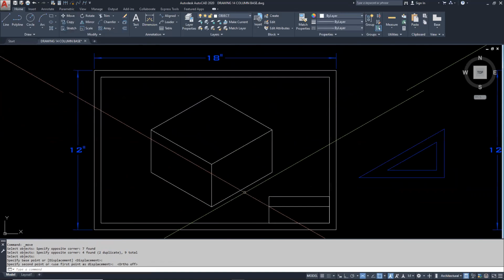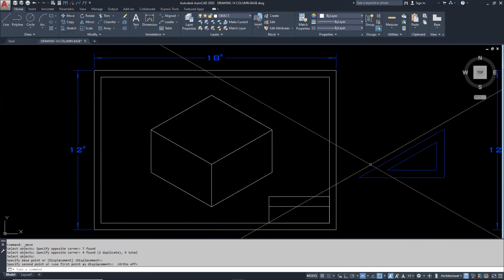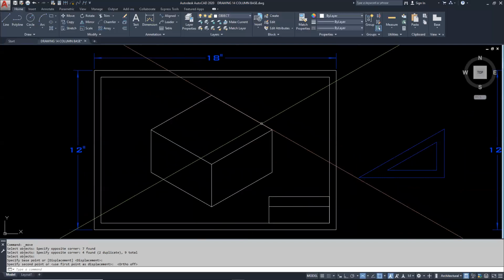Now, you are going to be doing this by hand, most likely, but you could do it with AutoCAD as well, of course. But you saw how I went off the page, but with AutoCAD, I'm able to move it. If you're drafting by hand, I highly suggest you draw this original cube for the size required on a piece of sketch paper fast. Then move it onto the paper. You'll get to place the object centered on the paper and have a finished product that looks good.